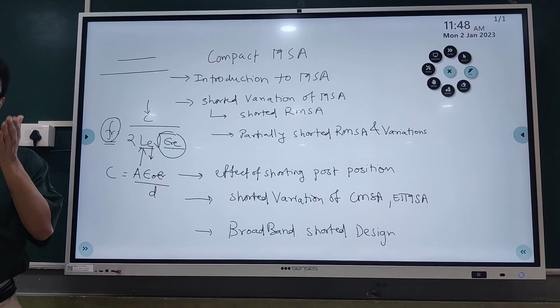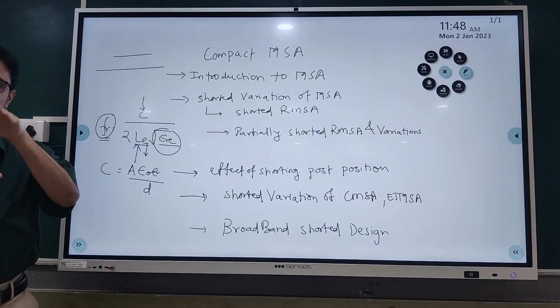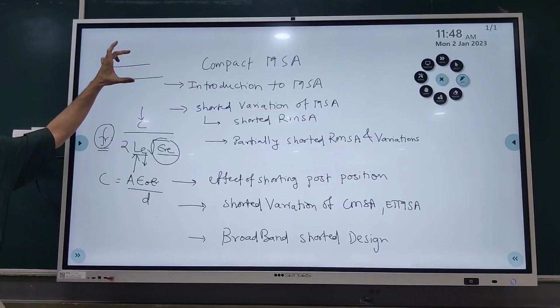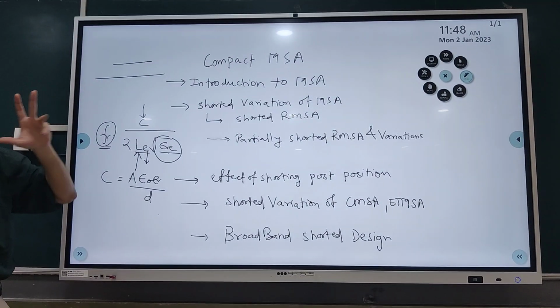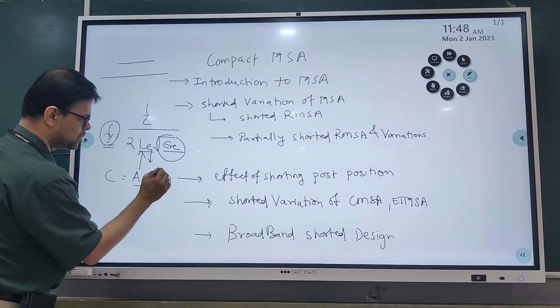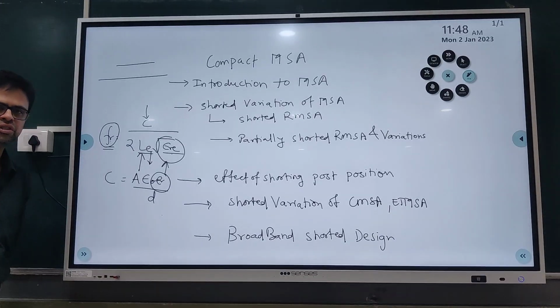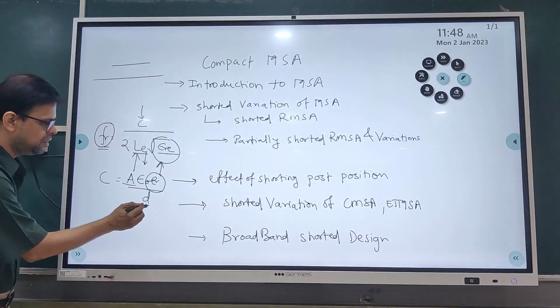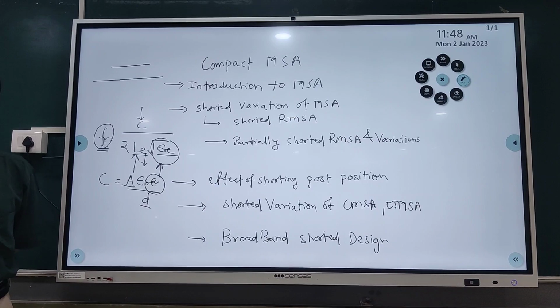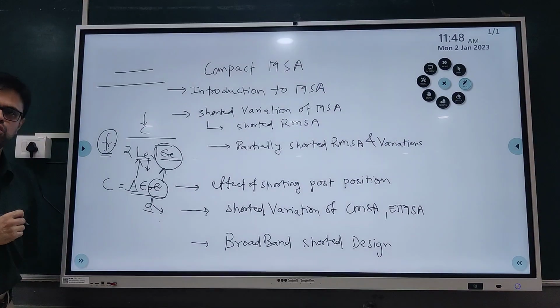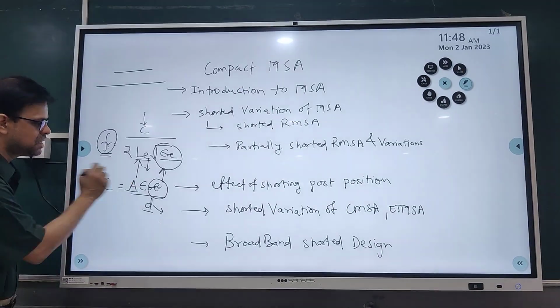It represents the capacity to hold charge within the cavity. A microstrip antenna is like a resonant cavity, so it will have some capacitance and some inductance. Now suppose I use a higher value of dielectric constant, keeping the other parameters as per the design frequency, with this as per your chosen substrate and this as per the design frequency.